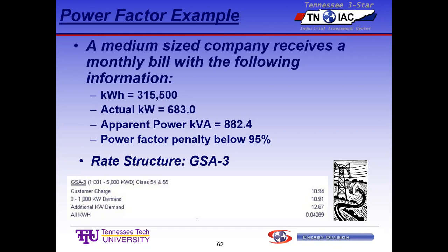They average it out so that, if you have large motors in a facility, when they start, the inrush current is like 6 to 8 times the normal running current. But it only lasts for a couple seconds. It depends on the inertia of the load, but it doesn't take long. And so if you did an actual instantaneous peak, that inrush current would help to set a peak.